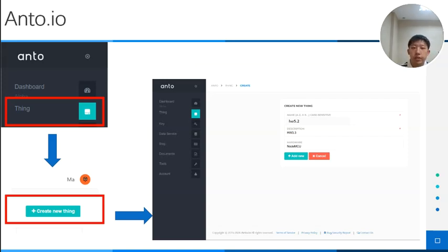The configuration is mandatory for communication, and every step is tailored to the homework code. First, log into the IoT platform and create a single device named SW52. This name must be identical to the one in the C++ and JavaScript code, without customization, so no typos are allowed.